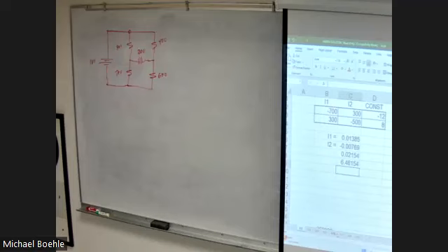I Thevenized around a component. True to form, everybody chose the wrong one to Thevenize around. I don't know if you guys remember this whole exercise, right? Okay. Because Thevenizing around the wrong one doesn't get enough information. What's the wrong one? Well, there's only one up there out of those 5 that is the wrong resistor to Thevenize.